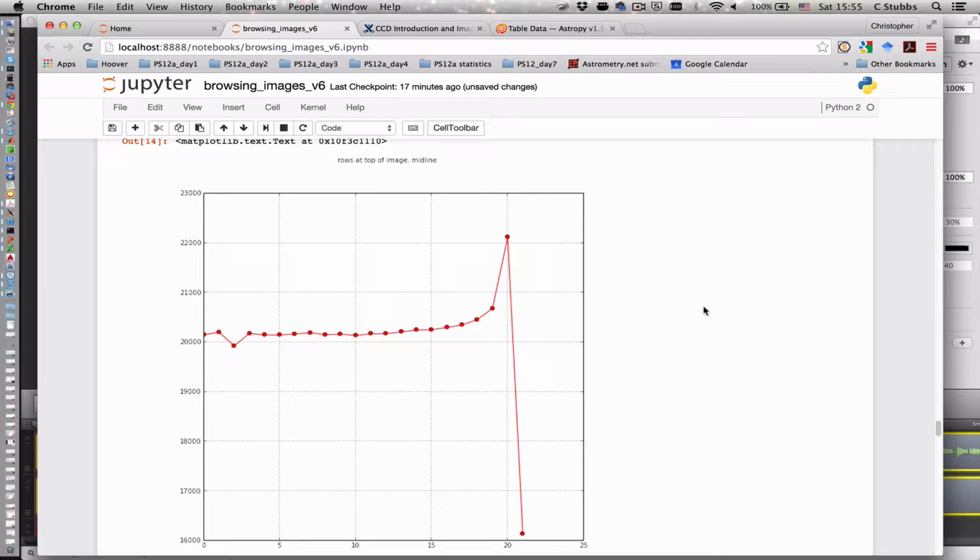And this is all phenomenology that we now understand. That midline barrier within the array actually produces a repulsive lateral electric field that pushes the charge away from the midline down towards the serial register. So this pixel's effective size is diminished, and the ones next to it have sizes that are essentially augmented relative to the mean, and that anomaly persists for 1, 2, 3, 4, 5, 6, 7, 8, 9, maybe 10 pixels into the array before it stabilizes.